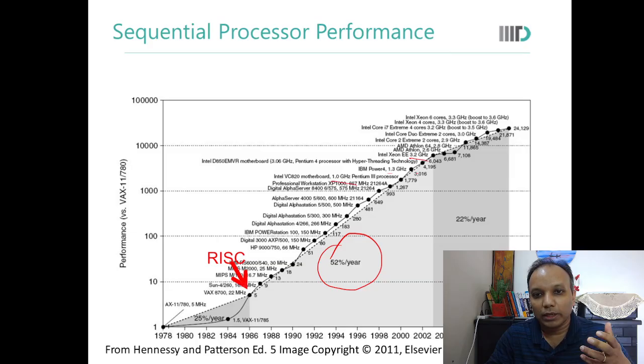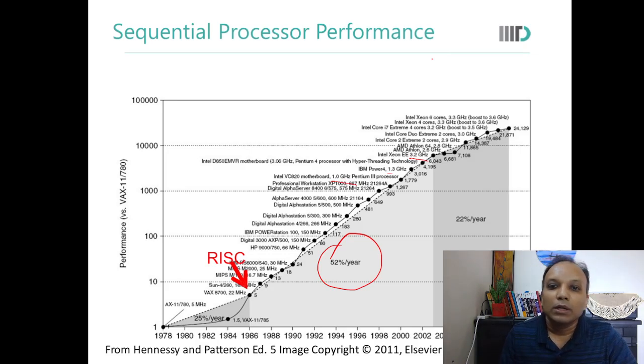But somewhere around early 2000, it was observed that we can't just arbitrarily increase the clock frequency of the processor any further, because of the kind of power dissipation the processors were experiencing, and the density of power was so high that the normal cost effective cooling mechanism, which uses, let us say, forced air cooling, would not be sufficient to cool the processor enough.